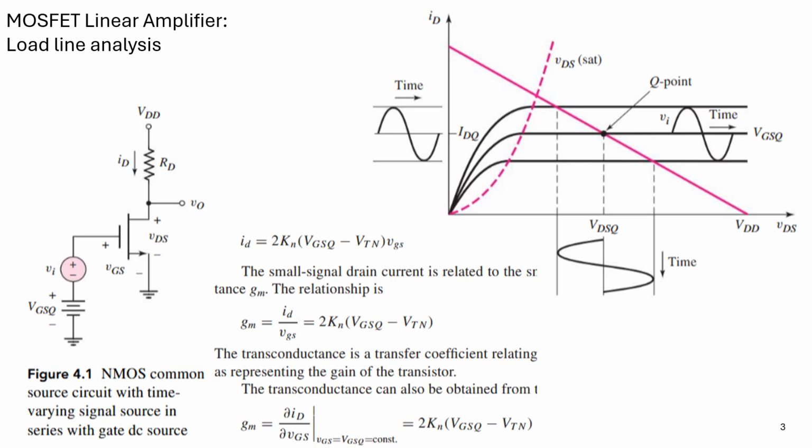So here is the MOSFET based amplifier. It contains the MOSFET with the drain terminal connected to RD, where we are going to collect the V out, and we are going to supply the AC input signal which will be amplified here. So we give the AC input to the gate terminal. This signal will be amplified by this amplifier, and our output will be collected through the drain end, and here the source terminal is grounded.